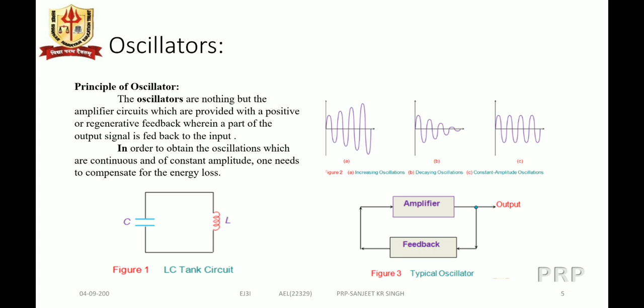So now the inductor will discharge its energy through the capacitor. In another way, it is charging the capacitor with the reverse polarity, the lower plate positive and upper plate negative. So in this way, charging and discharging of the capacitor takes place, and that makes a sine wave generated, as we see on the right hand side waveforms.